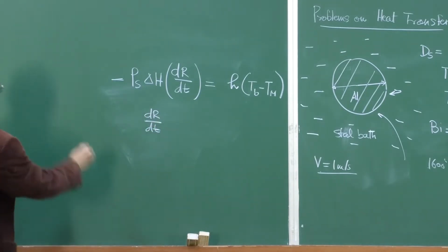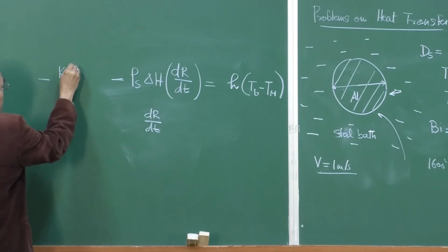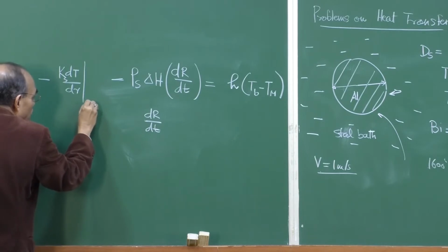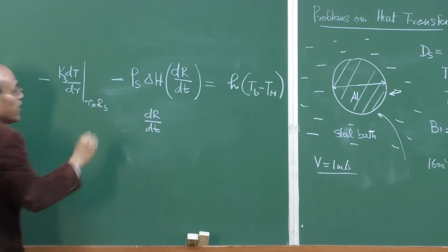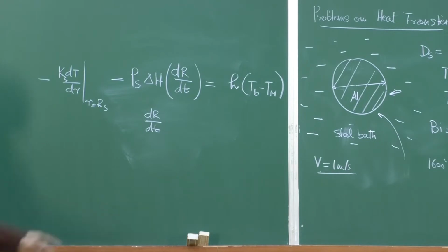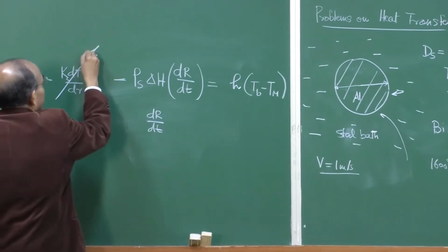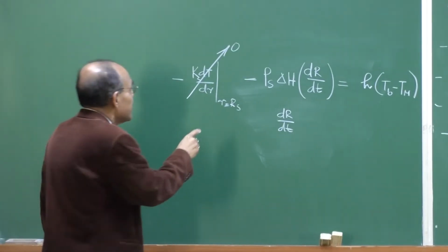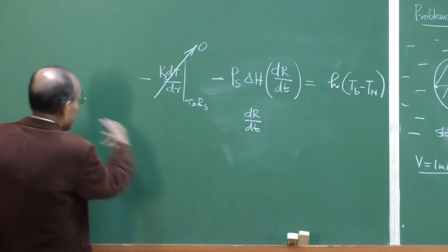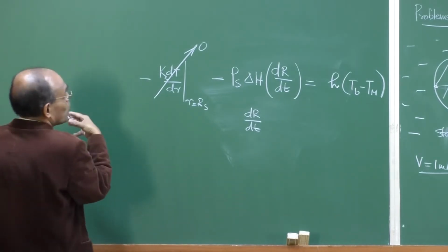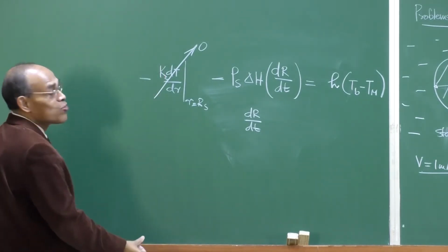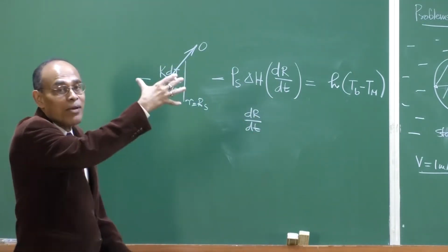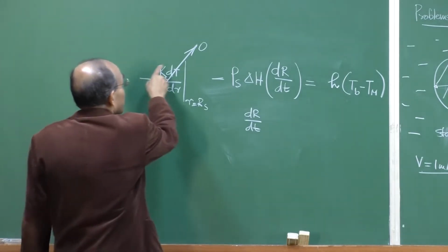actual equation would be, at the interface, the equation would be r is equal to R sub. This is the interfacial energy balance equation actually in the full form, but the moment we apply the lumped parameter model, this term becomes equal to 0. So, this essentially tells us whatever heat is going inside the solid transported because of conduction, whatever heat is consumed because of the latent heat, that is exactly equal to the heat which is being advected by the fluid right to the interface. So, this is the energy balance equation.